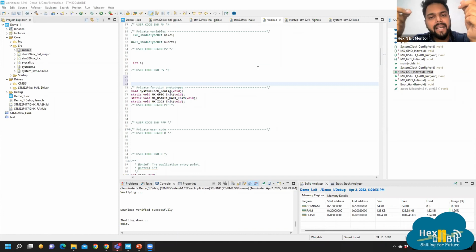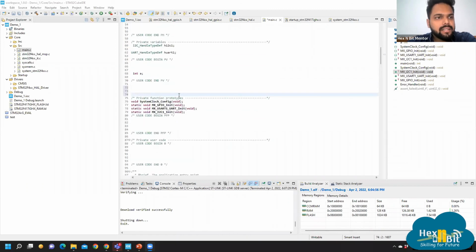Even the latency in 8-bit is high, for migrating from one peripheral to another, and there is also interrupt latency which is very high in 8-bit, but in ARM MCU it is very low. So these are two different architectures used for different applications. For small applications you can work on 8-bit, but for higher applications you have to move towards ARM MCUs. Okay, so this is one thing.